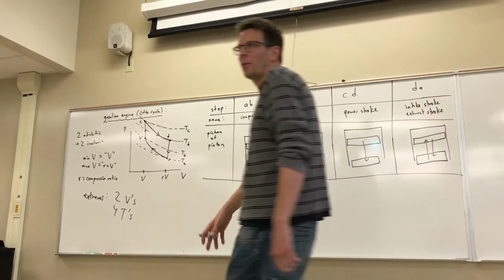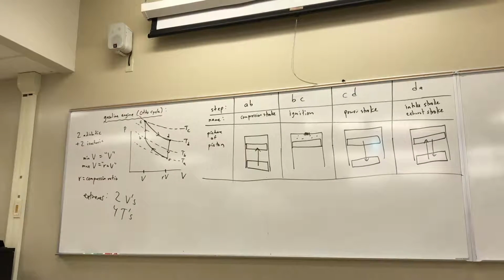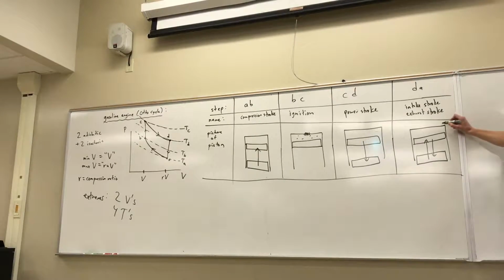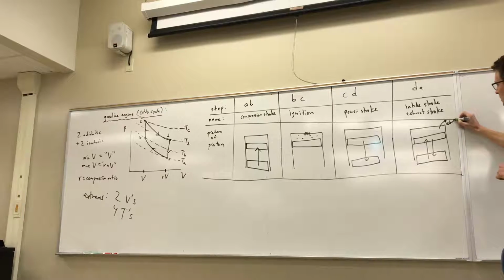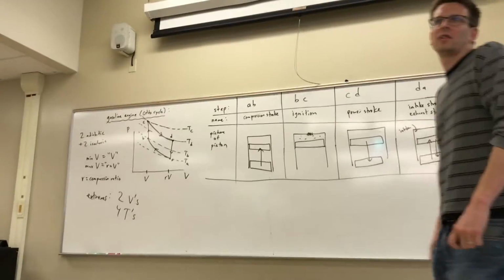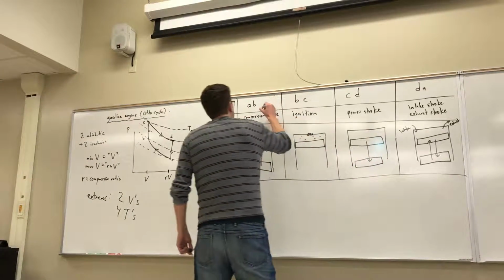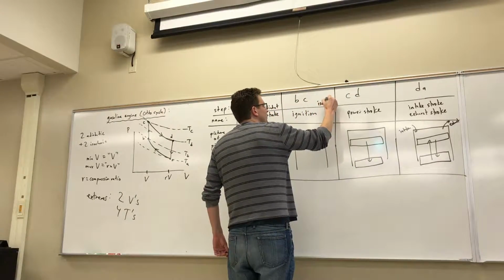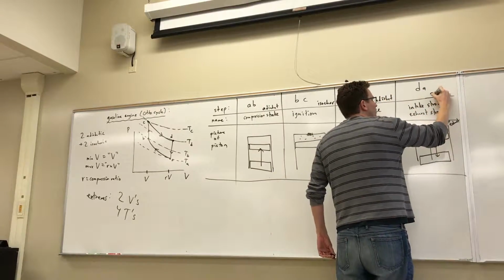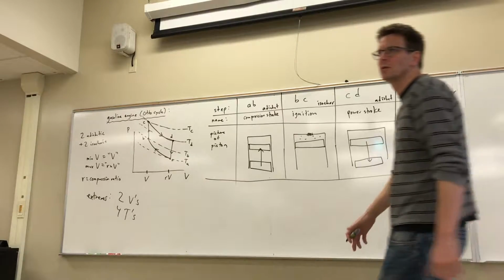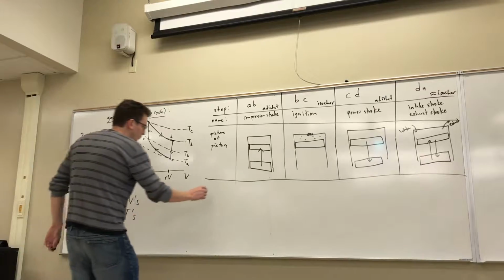So basically what we approximate is that all that you've accomplished during that is that you've taken what's in the chamber, which is warm smoke, and replaced it by cool, fresh stuff. So we've approximated it as an isochoric process, okay? We've gotten rid of the smoke or exhaust, and then we've taken in this new fresh stuff. But when you've done all that, you wind up with the same volume of gas, but at a lower temperature. So we approximate that as isochoric, okay? So again, if you want to label them, this is adiabatic, this is isochoric, this is adiabatic, and this we approximate as isochoric, okay? The net effect of that anyway.